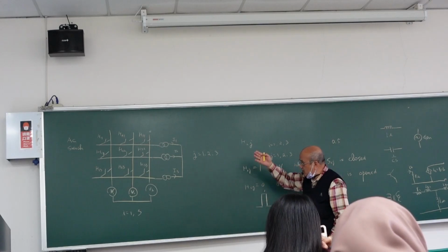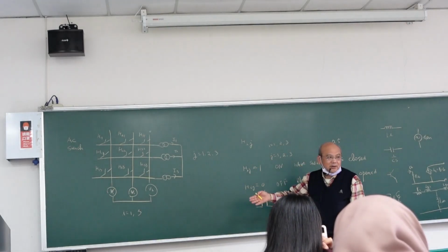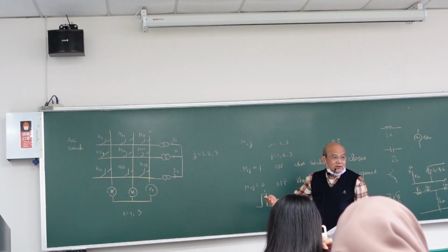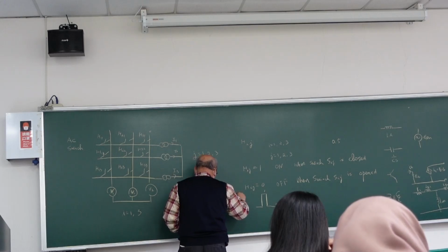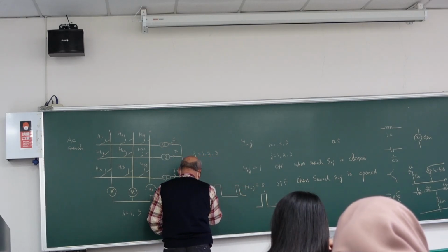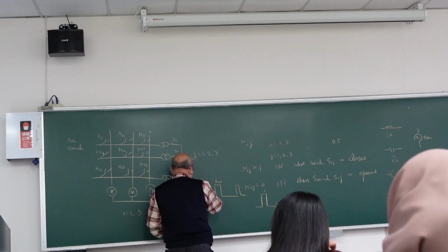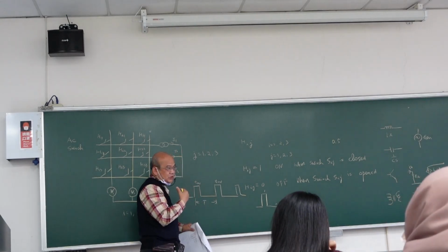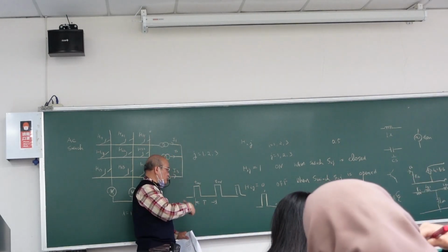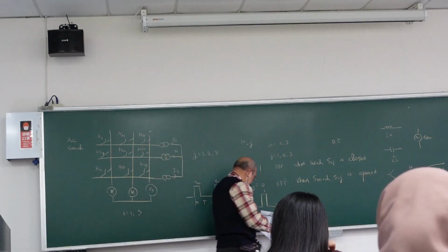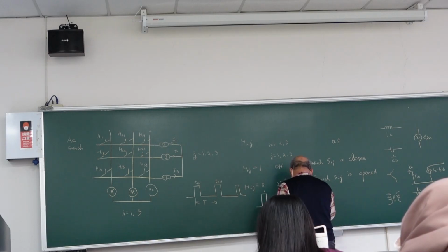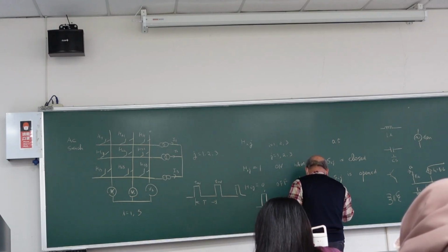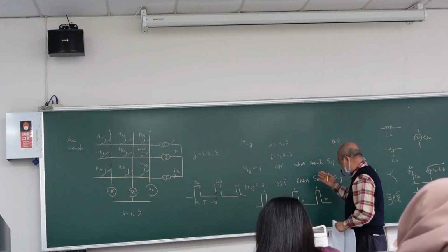But for power electronics, the switch operates regularly, repeatedly, right? So if you have PWM, then it is like this. So every period, you turn on for a fixed time. We call this the duty, right? So it is repeating. So 1 0, 1 0. So why is it repeating?